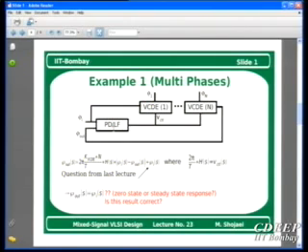Let us give an example. Suppose the input phase changes by just 1 degree, but instantaneously. The delay element has 0 latency, so the output phase can change by 1 degree. Therefore, the instantaneous error is 0. Therefore, the filter doesn't respond.